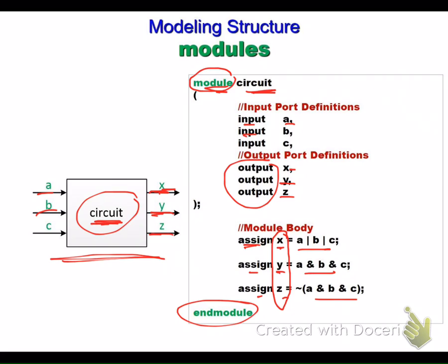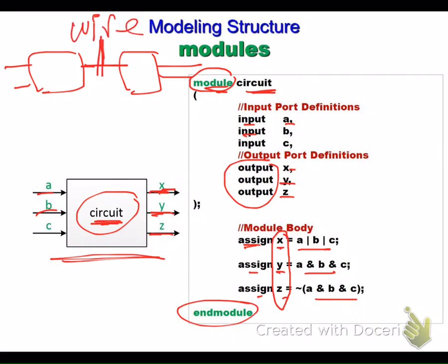If it is in between the design, then you will call it wire. Meaning that you will have a design here, you will have a design here, these are the outputs, these are the inputs, but you have something in between, which you can't define as an input and you can't define as an output. However, at a certain time, you would like to assign a certain value. In this situation, this will be a wire. But since I have this as an output, I can just call it an output, because this will be like a real output to the FPGA. They will be connected to one of the pins of the FPGA, and we will define it as an output. Okay?